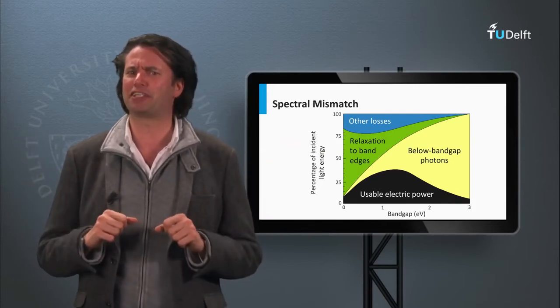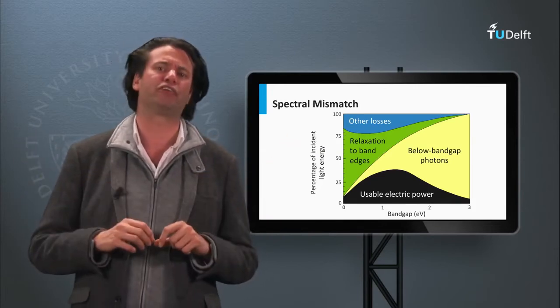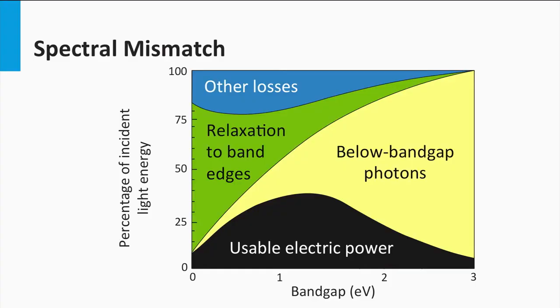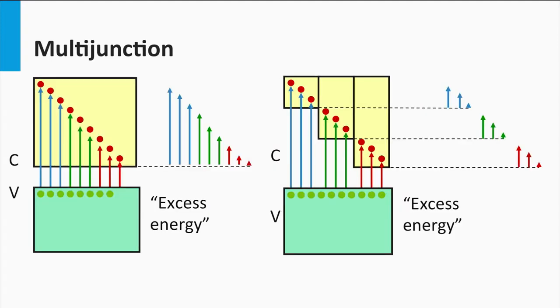Why does the 3-5 technology result in high conversion efficiencies? The 3-5 technology PV devices are based on the multi-junction concept, where more than one bandgap material is used. As discussed in week 4, using only one single bandgap material, the theoretical efficiency is limited by the Shockley-Queisser limit. Either a large fraction of the energy of the energetic photons is lost as heat, or the photons below the bandgap are lost as they are not absorbed.